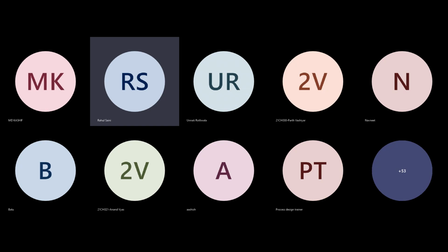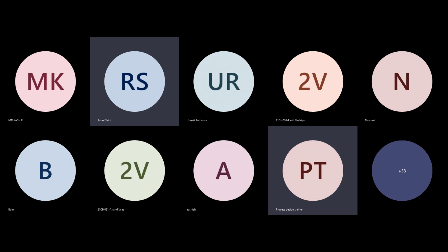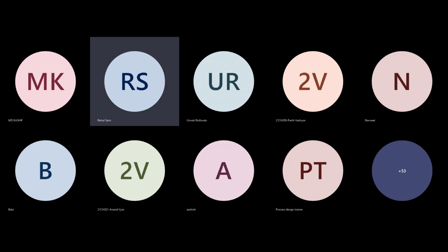And 317L, and we have just looked at the line. There are no traces of corrosion inside the line, but the line only erodes. There is no corrosion inside the line. It is because of higher velocities that erosion corrosion is happening. I have discussed with my team. We have concluded that there is only one possibility: the erosion due to the high velocity.